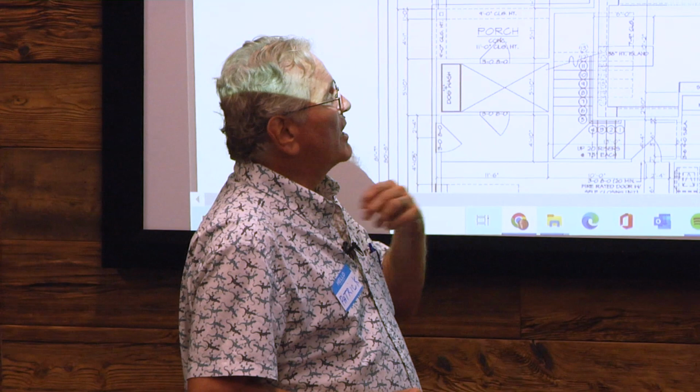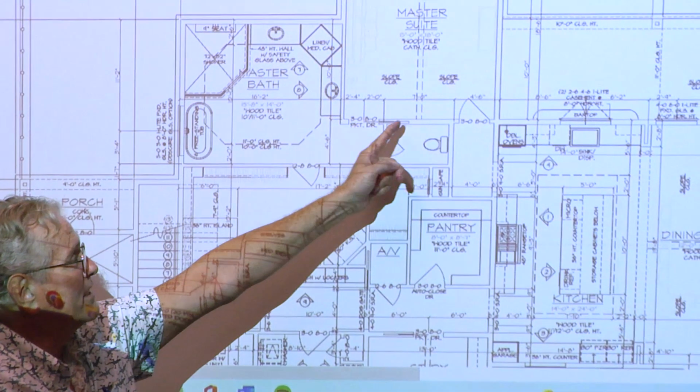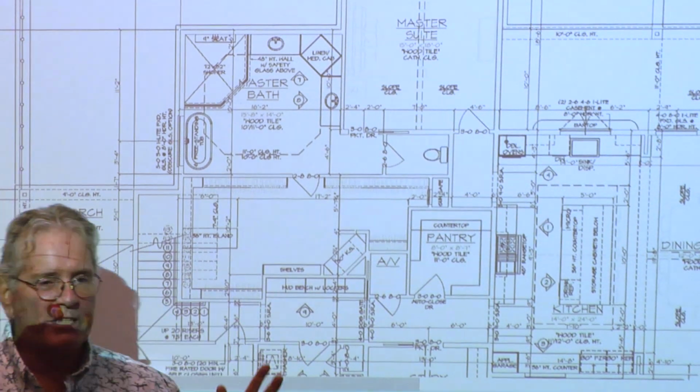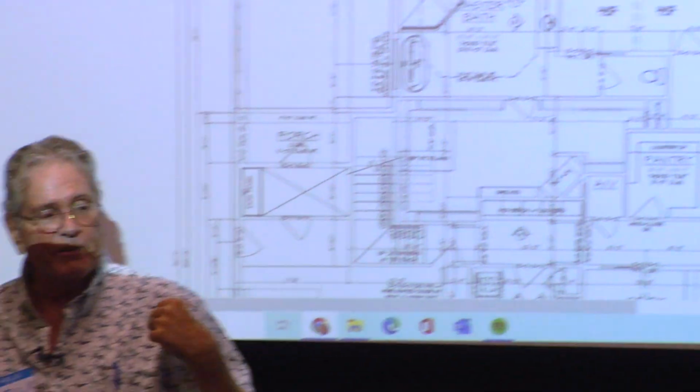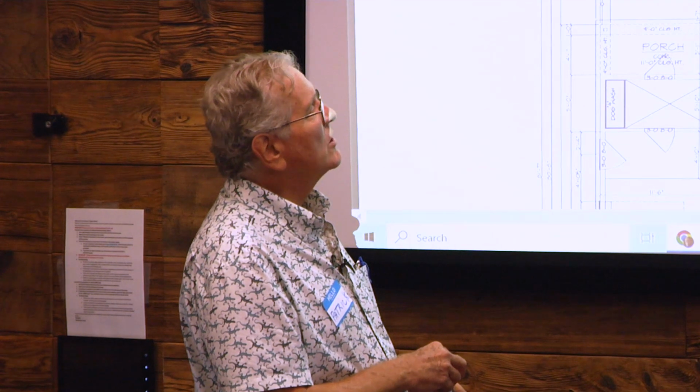A lot of people like pocket doors, but it's shown here as 6 feet wide because the edge of the pocket door comes back here. So the framer does a complete different frame job when he's roughing in for pocket doors. Just wanted to bring that up since it's a nomenclature that some people know and some don't.